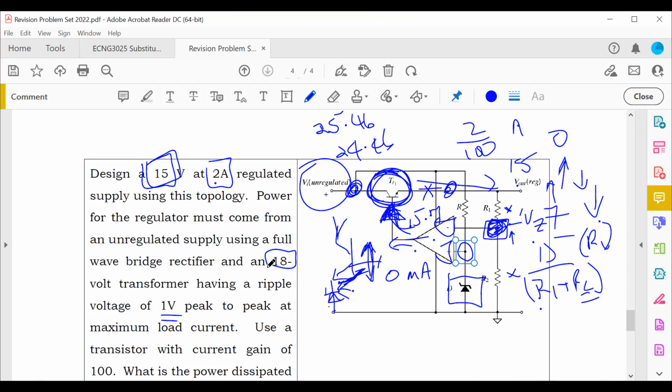Well, it is fairly straightforward. Depending on whatever you're going to do, at least you know how to size it, even if it's a 12-volt regulator to charge your car battery. The output will be about 14.5 volts. Normally, to charge a 12-volt car battery, you need about 14.5 volts.